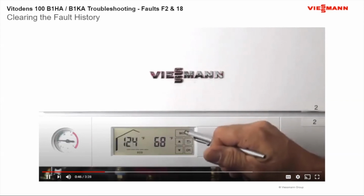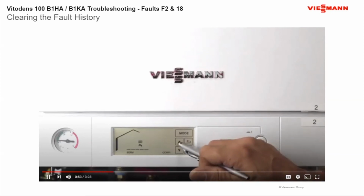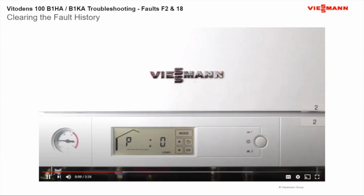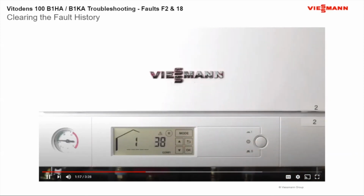We're going to start by hitting the mode button until "confi," or configuration, is flashing down here on the bottom. We do that by hitting the arrows, and now you can see confi is flashing. Once that's flashing, we hit OK, and now we're into password mode or programming. We're going to go up to the password, which for this one is number 10. Once we get to 10, make sure you hit OK, and now we're at our fault history.